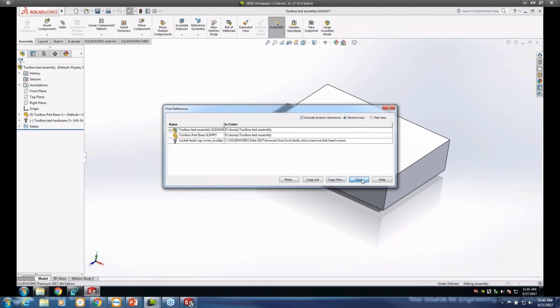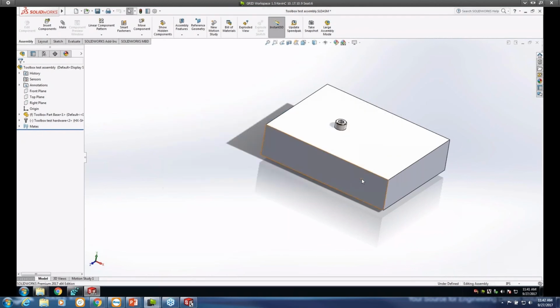So this is a similar issue in which components would be replaced, but in this case, this replacement is being caused by the SolidWorks toolbox option. So if you do encounter this issue the first time you open up this assembly and you see this, you can close out of the assembly, disable that option and reopen it, and everything should look fine. However, if it was accidentally saved with the default toolbox components, then those would have to be replaced, similar to what we did before with the file open and then replace references here.